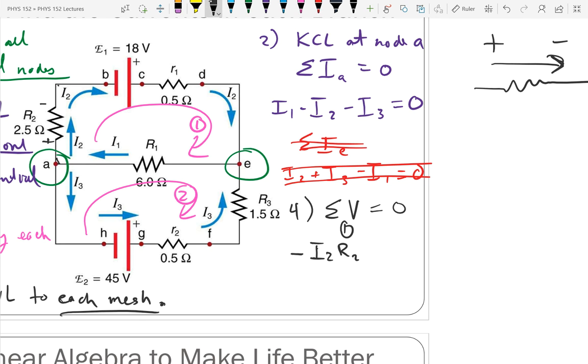Now we go through the circuit. We've gone through that resistor. The next thing we get through is EMF number 1. Is that going to be a voltage rise or a voltage drop? So should I use a plus sign or a minus sign? Good call. Keep going. I get to this resistor. Which side is positive for R1, left or right? Okay. So is that a voltage rise or drop? Okay. So I use minus. And what do I put now? R1 times I1. That's actually I2. Oh, okay.